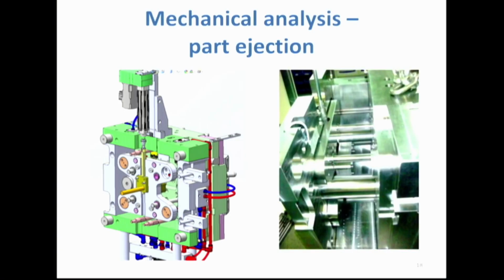And here you can see on the left picture the backside of the mold with the ejector plate, and the ejector plate is cut like butterfly wings to make it lighter because it must move fast. And of course we want to put inside the supports for the mold to give the mold plate more stiffness. And here you can see the mechanism crossing and the box where the two teeth bars meet each other.